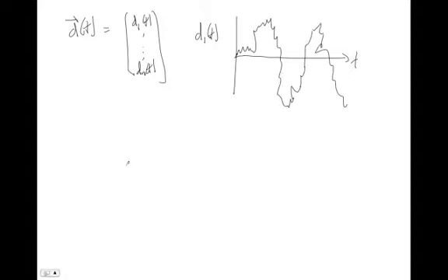And so in the Kalman filter development, there are some assumptions that are made on the properties of these signals. There are a few of these properties. One is that, so this is going to apply to both d of t and n of t, so both the disturbance and the noise. First, it's going to assume they're stationary. That just means they're not evolving in time. So at any given instant in time, the stochastic properties are the same as any other instant in time. They're zero mean and Gaussian.